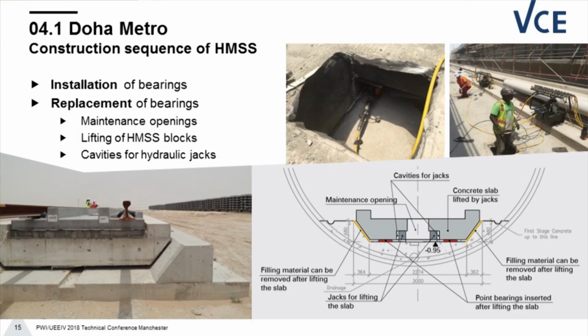So the system works, as I already said. We will place the jacks, we again will lift the block, and we can replace the bearings very easily. Here you can see one of these maintenance openings. Of course, it's quite narrow. The people working here need to be very, I might say, small in order to get in and to change these bearings, but it's possible. It was tested and it perfectly works.